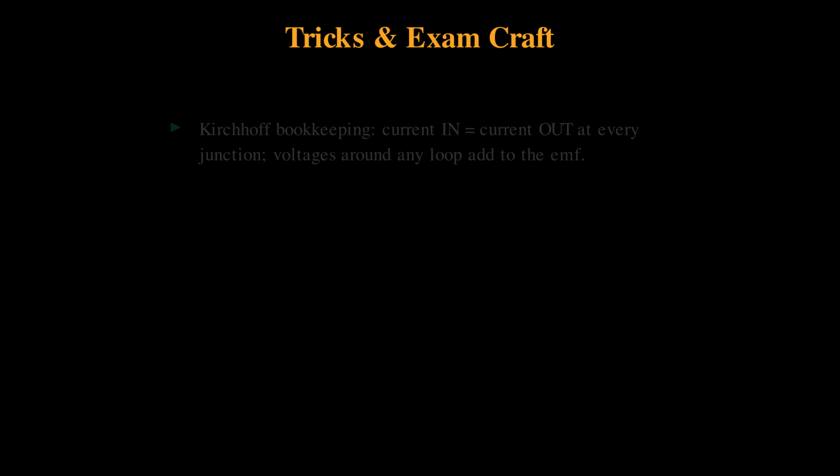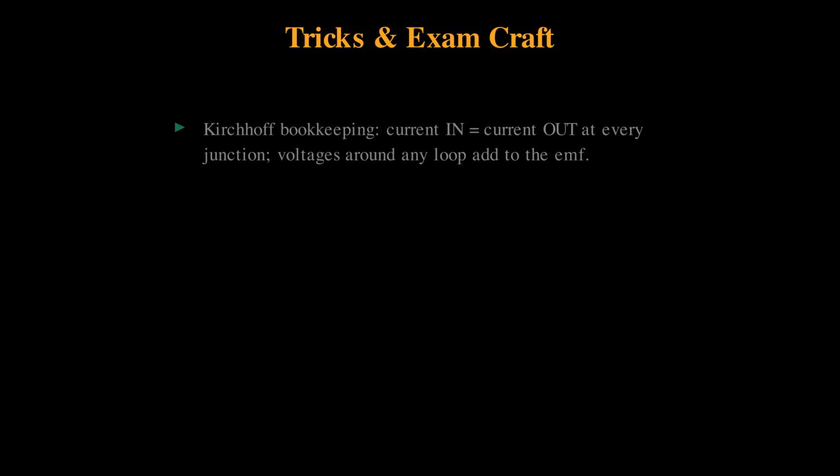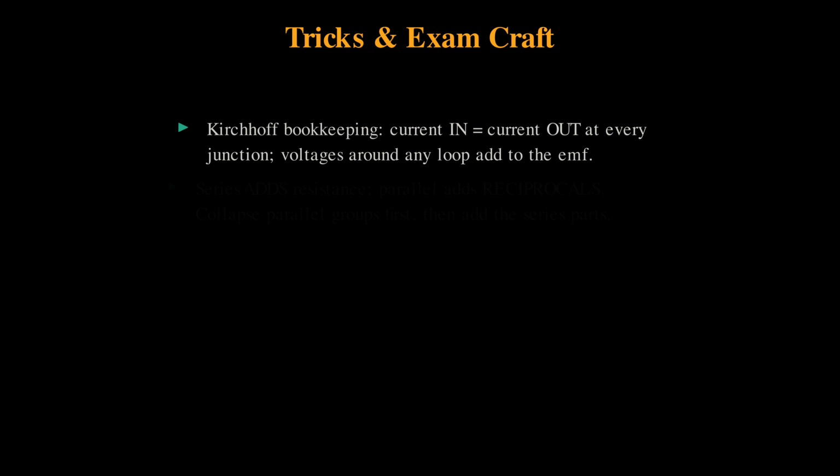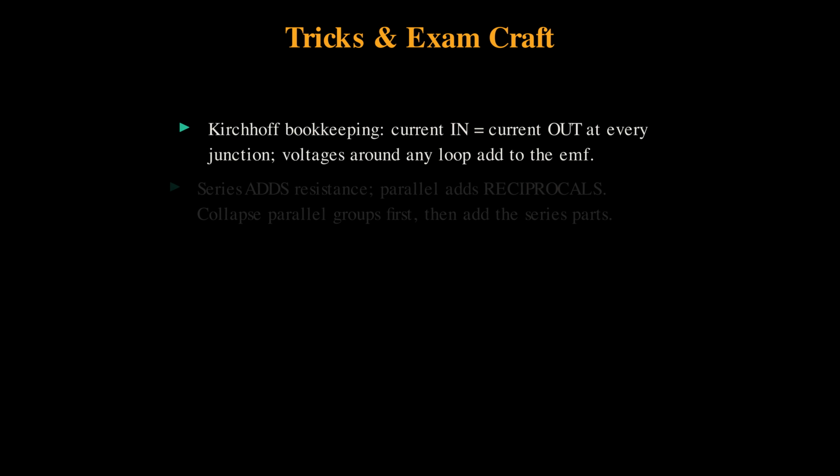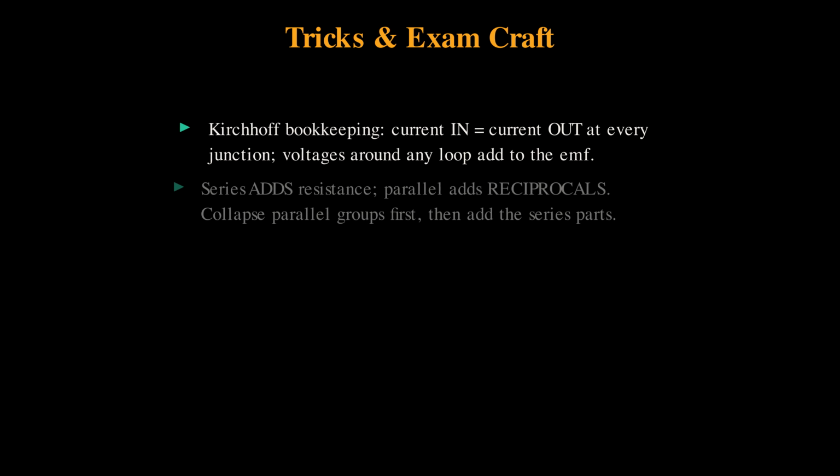Now the exam craft that banks the marks. 1. Kirchhoff is just bookkeeping. The current into a junction equals the current out, and the voltages around any loop add up to the EMF. Label your currents and directions before you touch algebra.